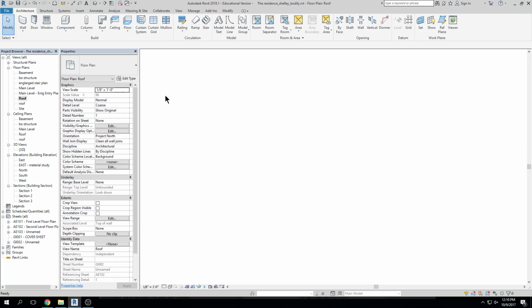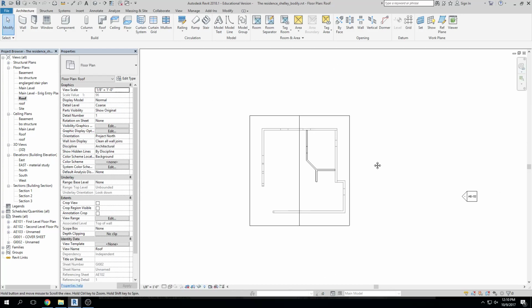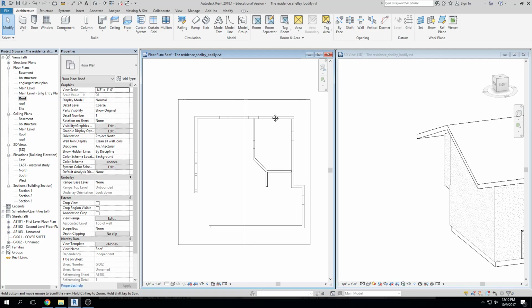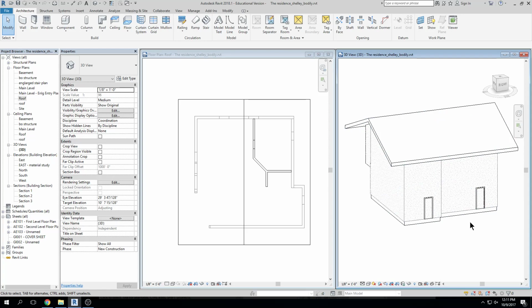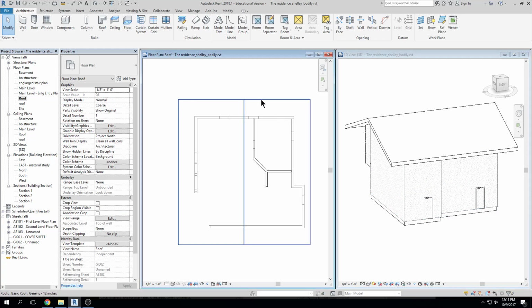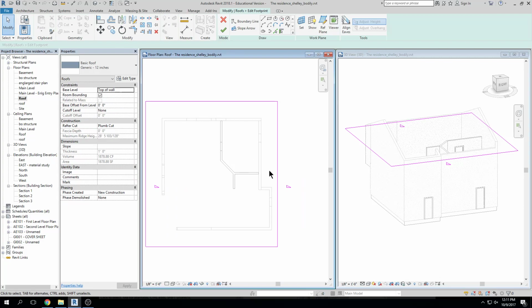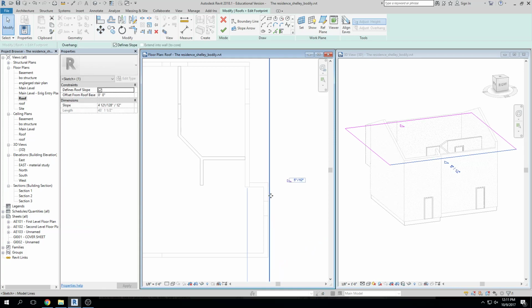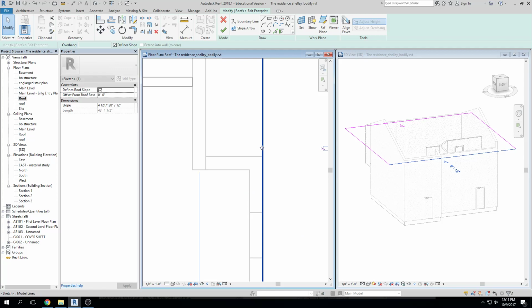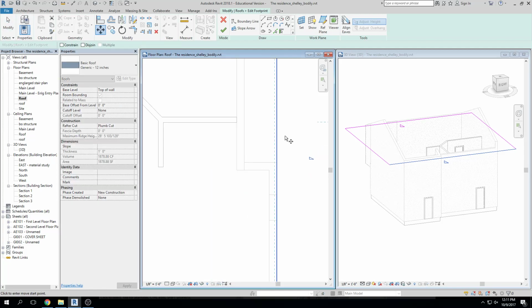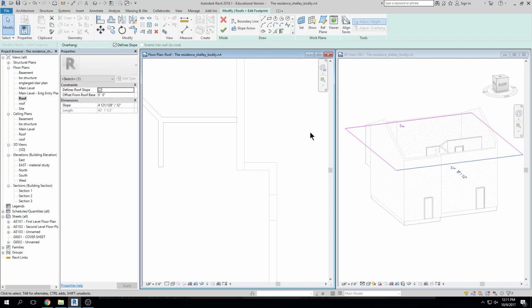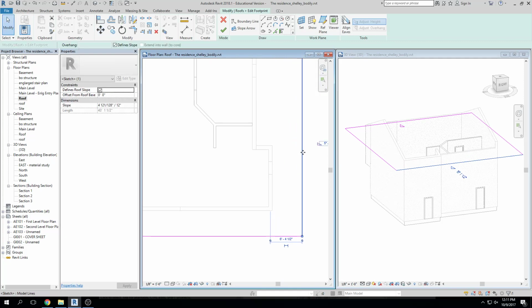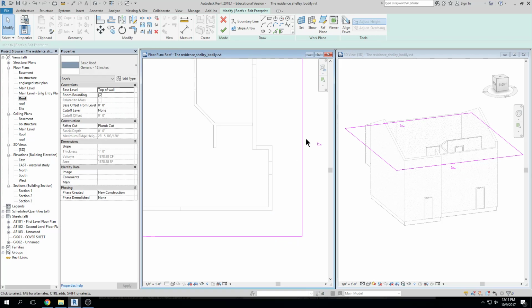And now we're going to go back to my roof plan here. WT. I keep trying to offset the one side so it's got more of an overhang over the porch, but it won't go. It just keeps giving me 3 feet. So if that happens, I'm going to hit edit footprint. I can grab this and I can MV, move, click, click, and move it. Maybe I want it, I didn't quite move it where I wanted it. If I move it to the wall, and then MV, click, I could type 6 foot, enter, and it moves it out 6 feet. So instead of trying to use the offset when you draw, if it's not working for you, which again, you'll get used to this, you can move these back and forth to get what you want.